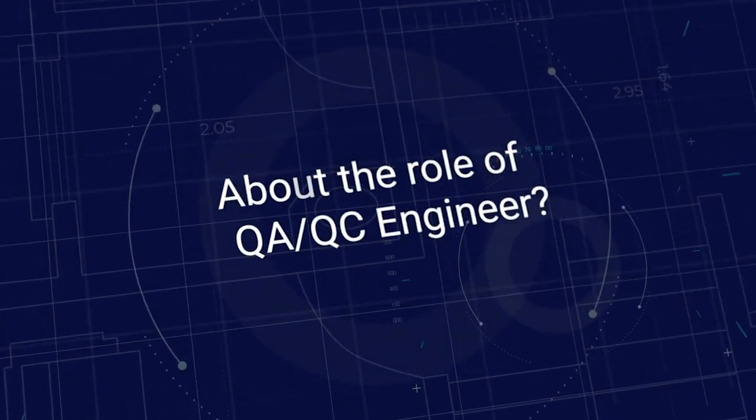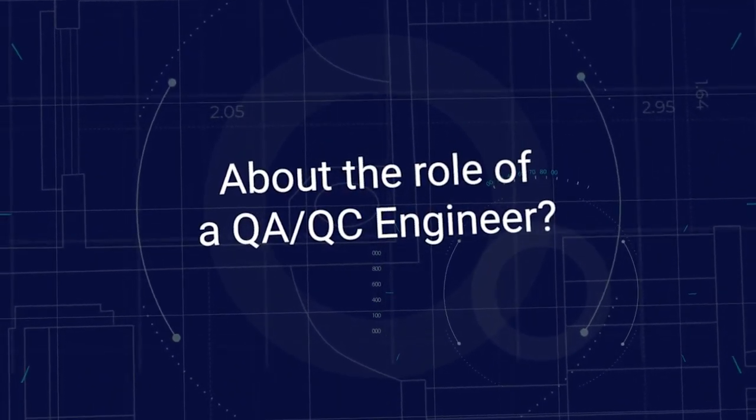Now let's see about the role of a QA/QC engineer. Quality checking engineers are involved in checking the quality of materials used for construction. They check the quality of concrete used for construction by a few site tests like slump cone test, flow table test, etc.